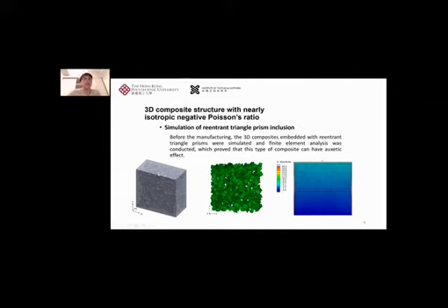And then we imported this model to the finite element analysis software, Abaqus, to mesh it to create this FE simulation. And then we added a force to compress it. If you can see from the right-hand figure, the gap between the red line and the blue rectangle, there is a very small gap. This shows the lateral contraction of these overall structures, which proves that this type of composite can have auxetic effect.